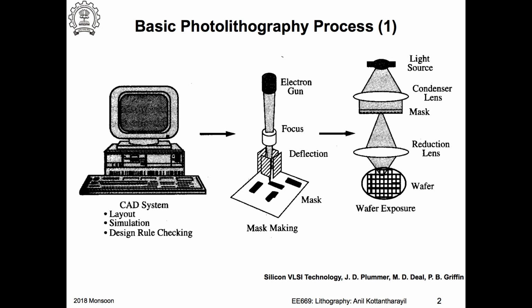You have a computer generated pattern. So the electron beam lithography system would have what is called a pattern generator. That just generates the pattern and deflects this beam. And you may actually have an XY stage for this plate, so it is moved in X and Y. Small deflections can be achieved using plates where you apply electric fields. So this can all be modulated or controlled by the computer based on the layout that you have created.